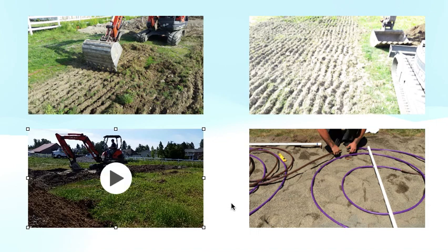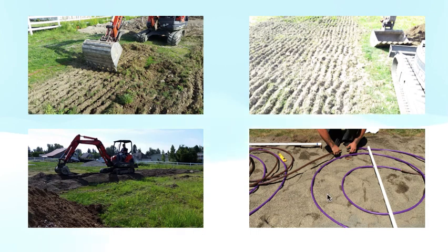A point that we haven't discussed yet: the coils themselves. The coils are all going to be in a straight line, all connected to each other. They need to be level. The rest of the basal area does not need to be level. They have a minimum amount of sand that's needed. Again, refer to your designs, refer to your engineering, and your county-specific requirements. But the only place that's required to be absolutely level is the area where the coils are.